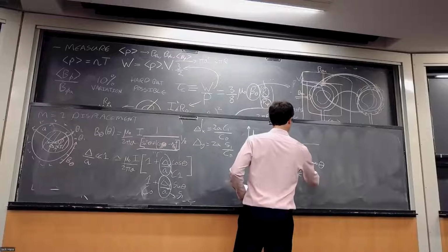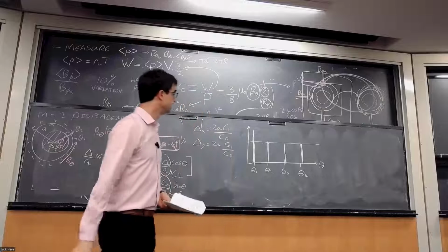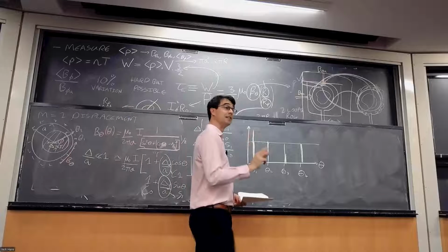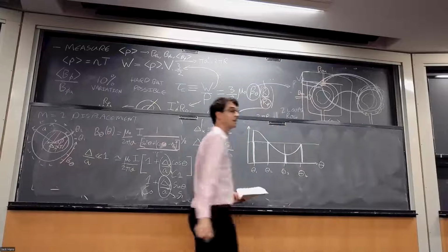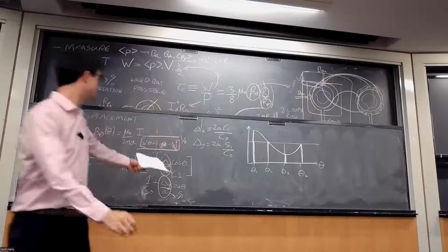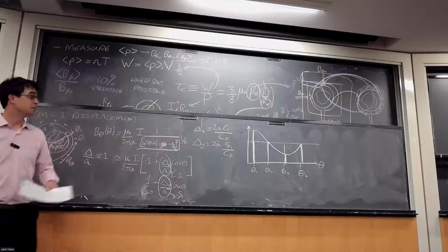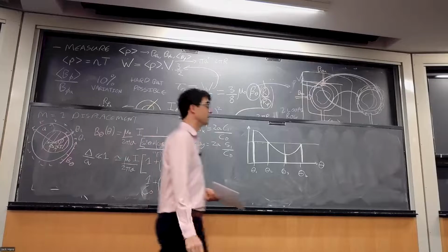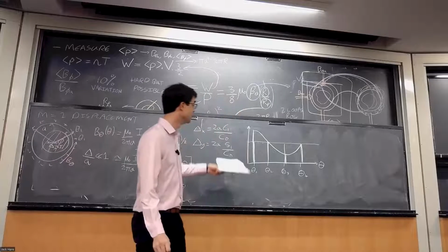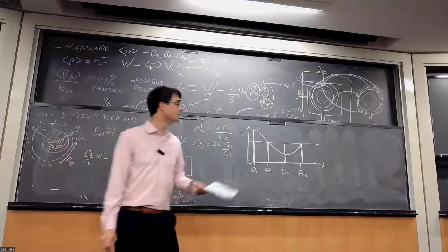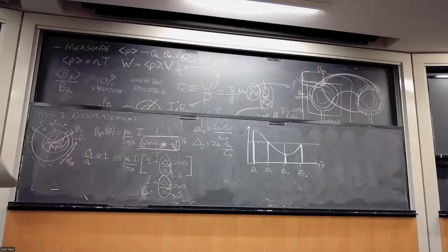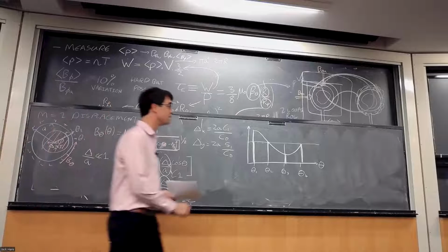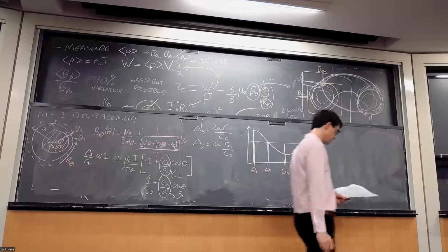And you'll notice that in this case I've got 4 sensors, and I can just about reconstruct the cosinusoidal variation there. You'll find that very interesting when you come to the P set, because this sort of question is fundamental to how many B dot probes you need to measure some displacement. So thinking in terms of the Nyquist-Shannon sampling theorem, things like that might get you a long way. So, cool.